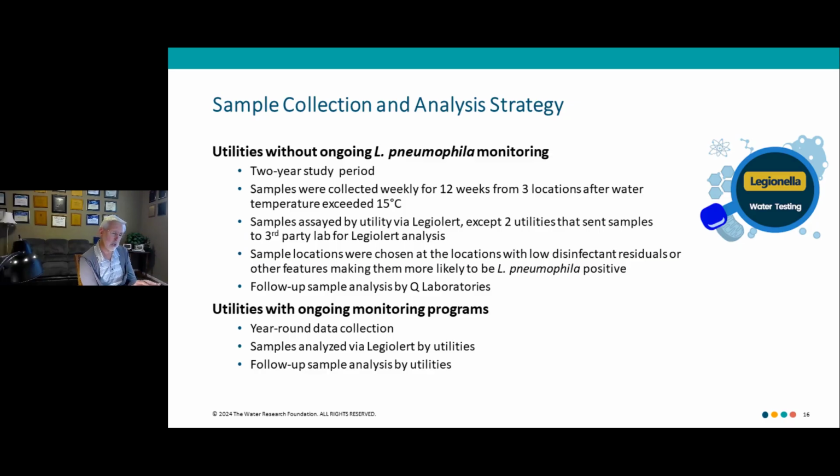We asked them to choose sites that they thought were more likely to be positive for Legionella, that is, sites that tend to have low chlorine residuals. We had some of the chloraminated systems specifically go out during nitrification events when they knew chloramine residuals were low. So the utilities did a really good job knowing their systems and trying to find the more problem areas.